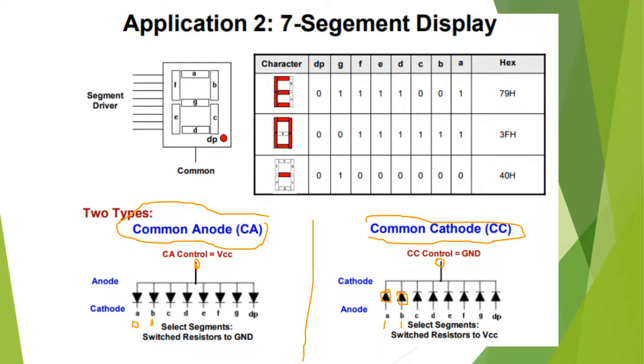You already know this from the 200. Okay. So now, for example, we have a 7-segment display here. The A, B, C, D data is coming from here. If we want to display E, look here, what is E? We have to turn on this A segment. Then B is off, C is off, D should be on, E should be on, F should be on, and G should be on. Dot point off. Then we can see the character E.